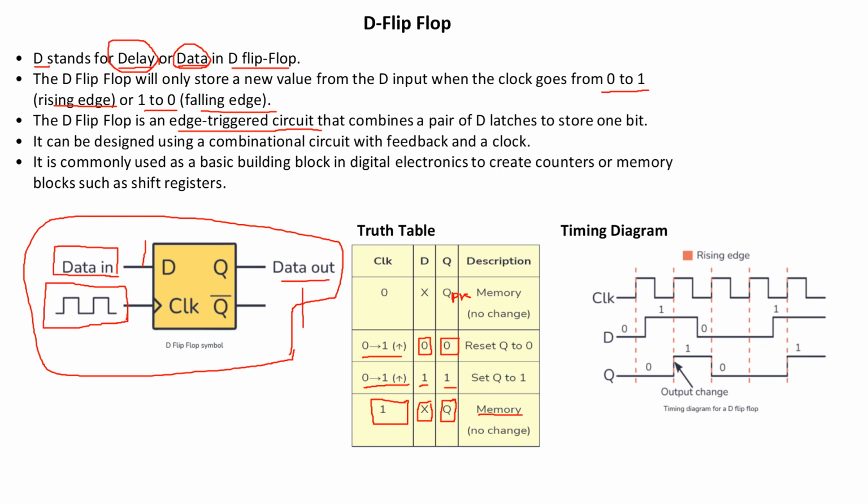The same you can understand from the timing diagram. So I have taken the same rising edge flip-flop. This is my clock, and this is my rising edge, so I will mark it, and this is my data. You can see at this rising edge my data is logic low, but here my data will not change.